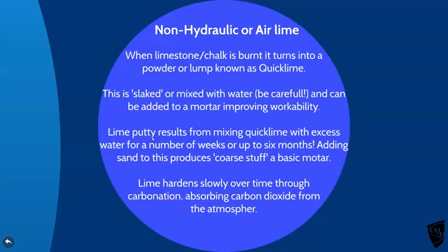It's slaked. You heard that on the video there, slaking it. And you can mix it with water. It's an exothermic reaction, so if you've got a bucket of water and you put a bit of lime into the water, you better be standing back because it's almost explosive. You always add the lime to the water, not the other way round.